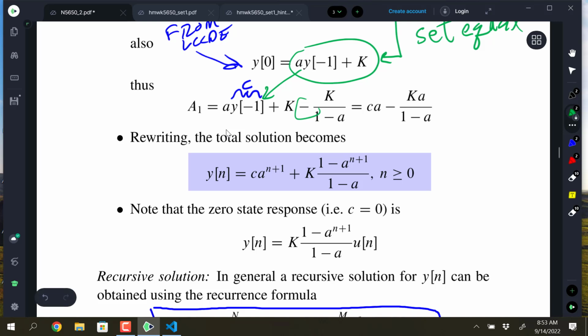We actually have seen something kind of similar to this with that convolution sum equation we did last time. Remember where we worked it in the 3 pieces? We got something pretty similar to that. That was a little bit different because it was a pulse rather than just a step. But if you look at the full equation in blue there, you can kick back a little bit and say, what is this? It's a first order difference equation, and the first term there is the transient response. It's the portion that's going to die away as n goes to infinity.